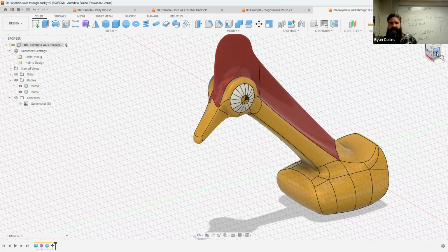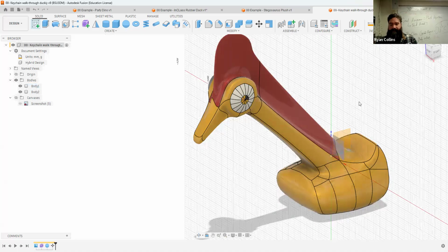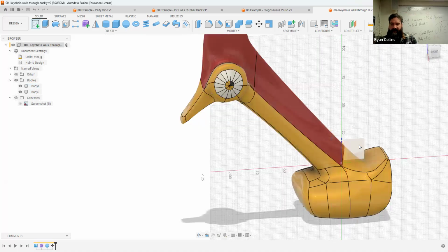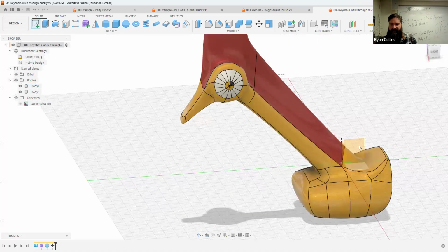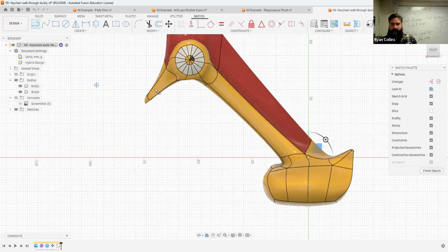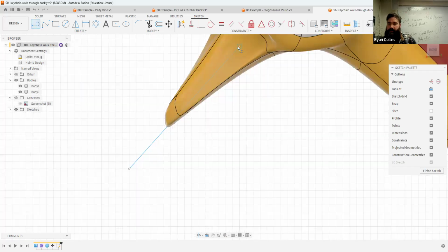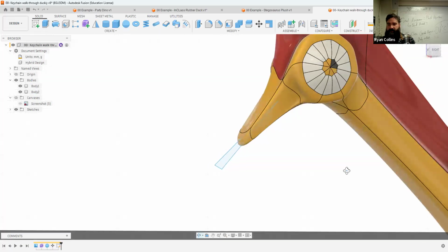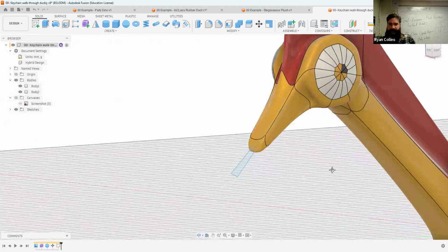What I mean by that is, let's start a sketch. We're done. We're finished modeling with the form. Take the YZ profile. So I'm sketching from the side, and let's simply draw a line from the center outward, and let's make it even more so. Connect the dots, and we have a wedge. Finish sketch. You can see that it's smack between.